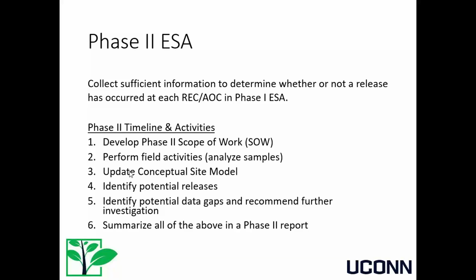What we call the conceptual site model is essentially, and I will not get into that a lot, how what would be the migration pathways and who will be impacted. So understanding how the contaminants might move and be transported into the subsurface. And essentially, the next step is to recommend whether we need additional investigation or not.